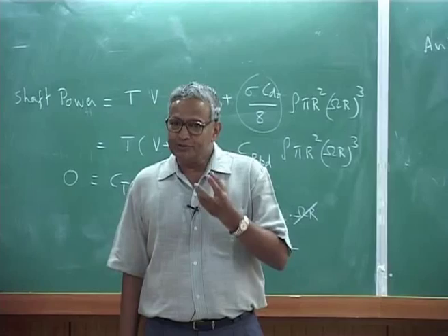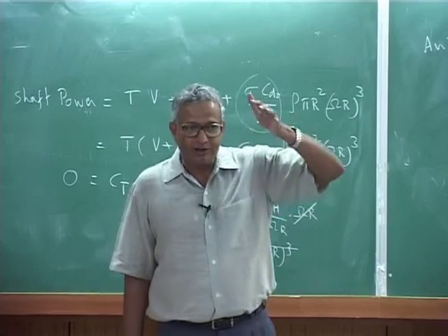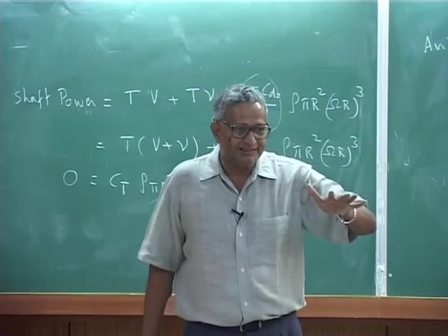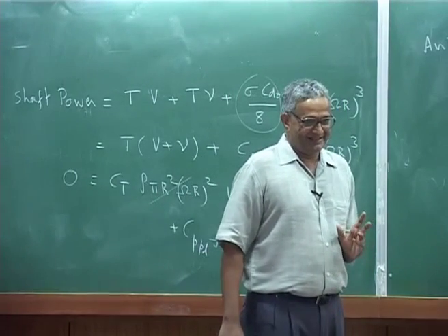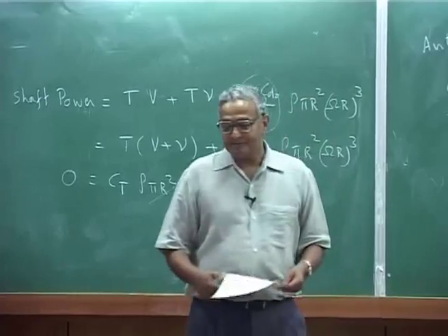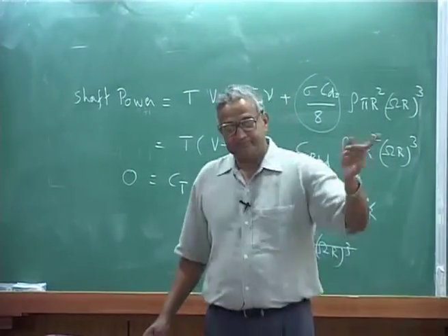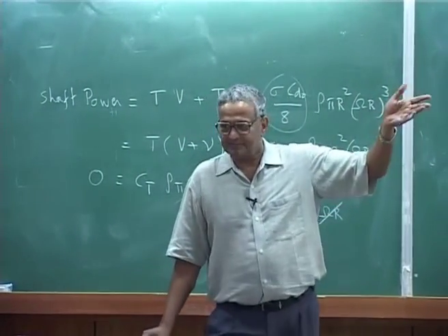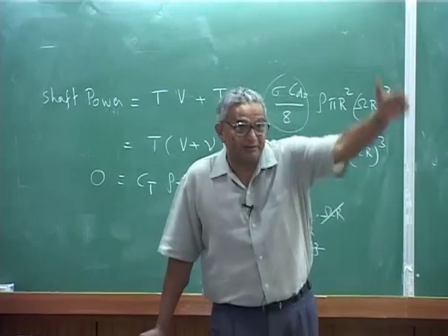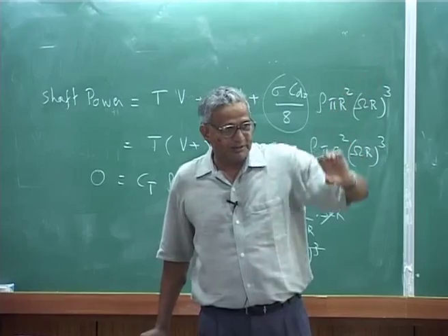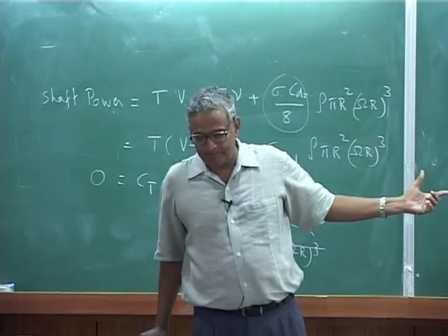If that value is small, that means your auto rotative descent velocity is also small, okay. And that is how in the selection of airfoils, because of course, it is not that one airfoil you can choose, because the rotor blade is a long blade every section, but this is one of the interesting part, okay,